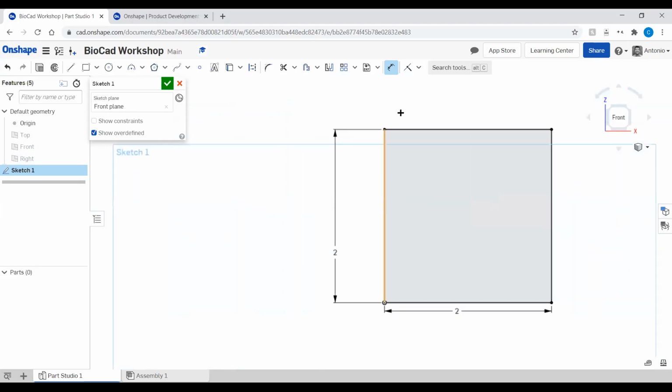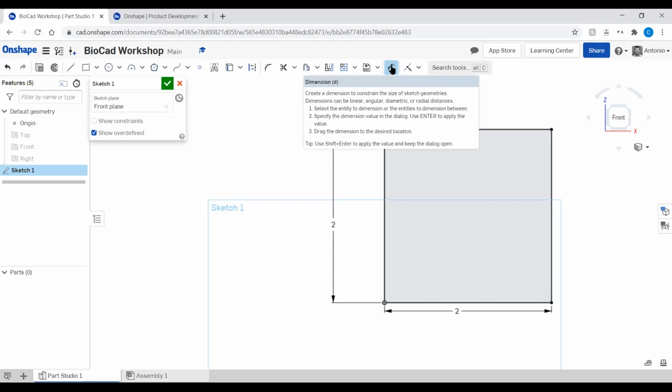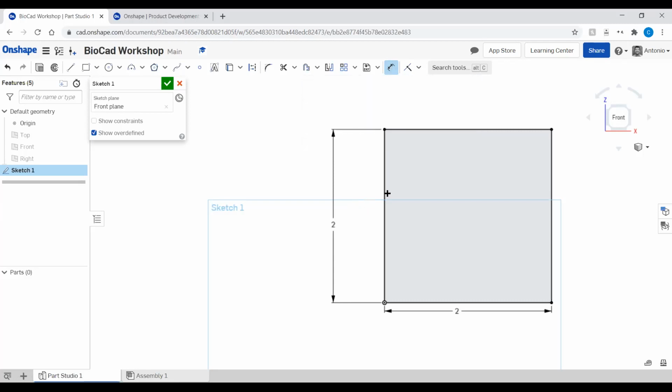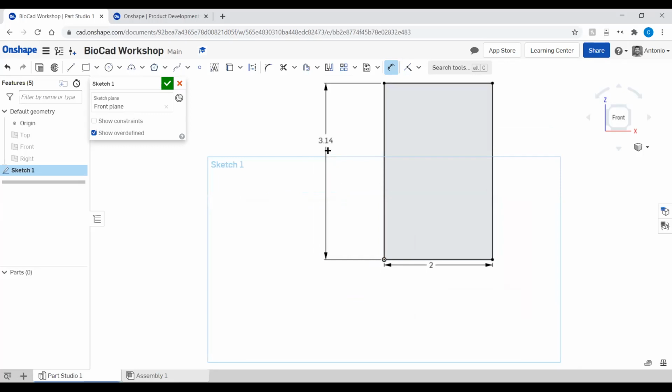How do you actually get the dimension using the dimension tool? How do you get the dimension, you asked? Yes. So you just click this dimension tool right here. It should be next to where it says DXF. You can also use the keyboard shortcut, just D. Right, and how do you specify the number 2? So if you click something, so I'm going to delete this dimension here, for example. Cool. So to specify the dimension, you click the D, and then you click the place you want a dimension. Click it once, and then it should let you type it in. But if you say you typed in the wrong thing, so you wrote in like 3.14, you can actually double click it again on the number and just type in what you want. Cool, thank you. That work for you?